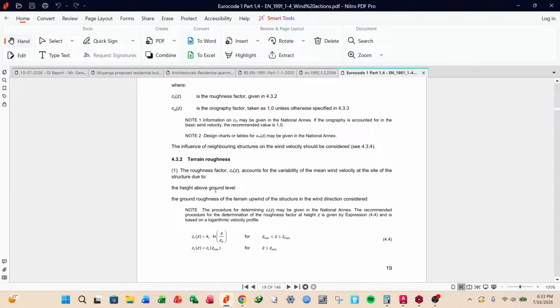So the slabs are rigid in that horizontal direction. They are stiff enough to actually take up or absorb all the wind from the cladding, so from the walls. The wind is received by the walls or the claddings, but is taken up by the slabs because they are stiffer in that direction.